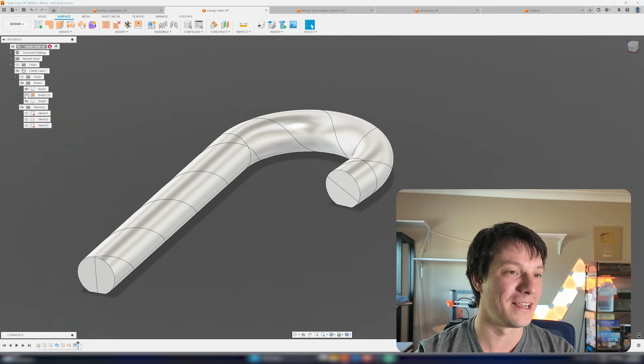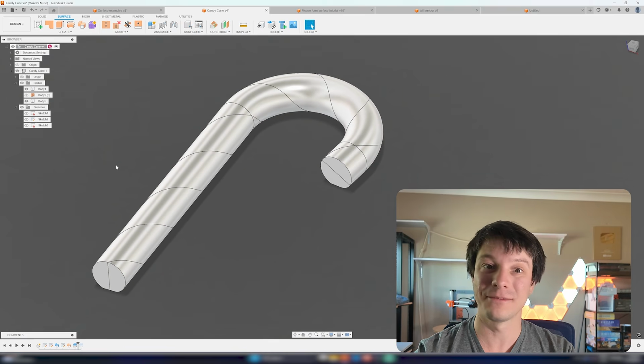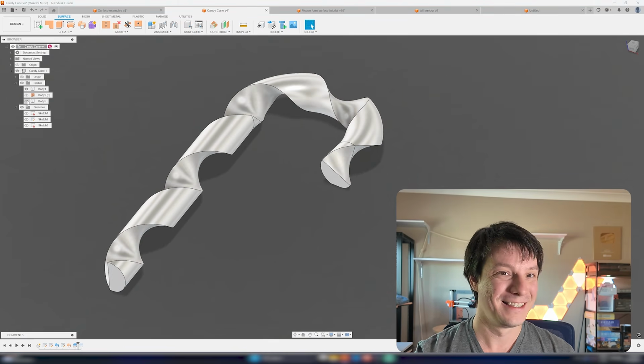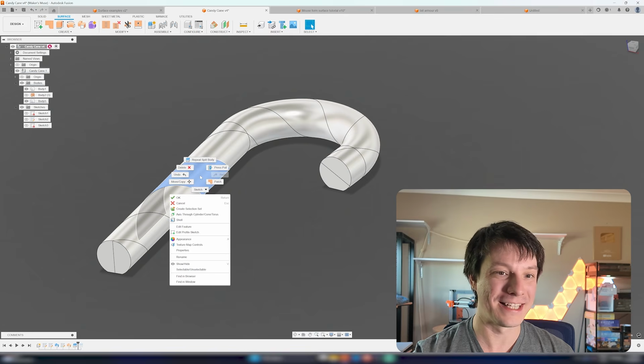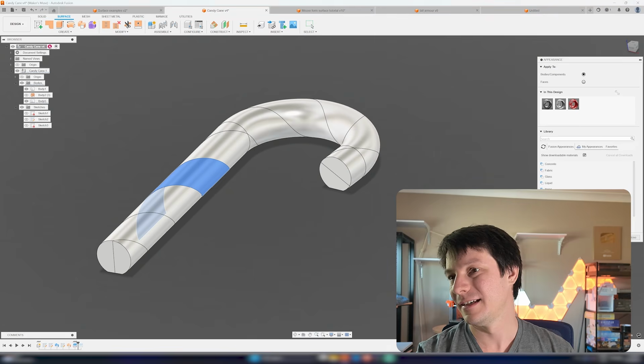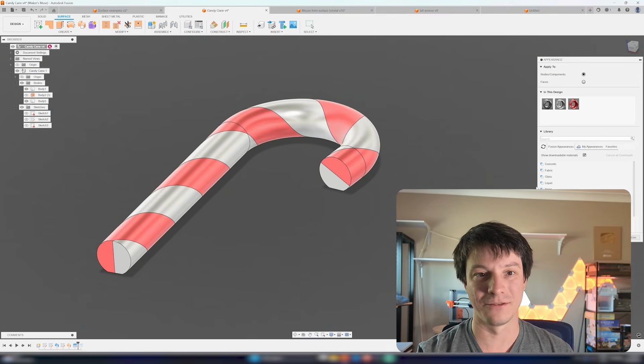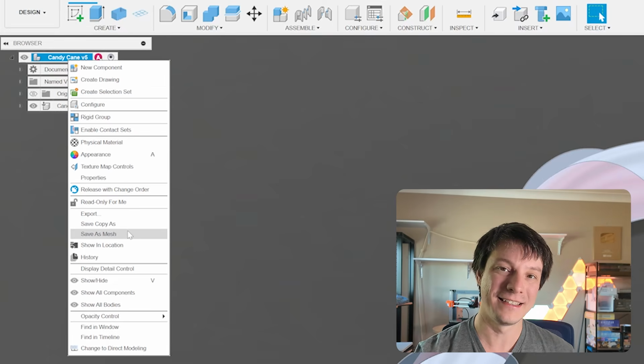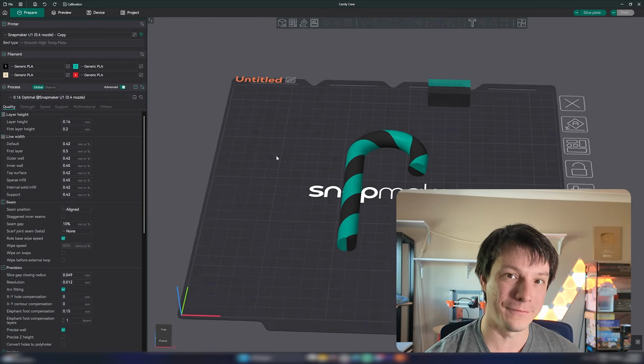And then I'm going to hide my surface. And just like that, we have a solid body cut into two bodies. Like that. Really neat. We can add some color. So let's go to appearance. And let's just chuck in color to one side, like that. And we can now export this as a mesh file, a 3MF, with two bodies within it for multicolor printing.